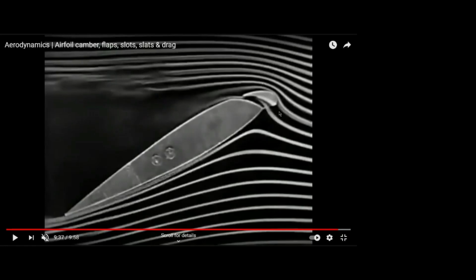Okay, so yes, the same. Tell me more. If you use this leading edge slat with a slot, that is a gap, you can maintain the attached flow on the aircraft. If you can maintain the attached flow, lift automatically will increase, right? Also, mostly this leading edge slat, they will deflect it downward, so that they will increase the camber also. Is it clear?